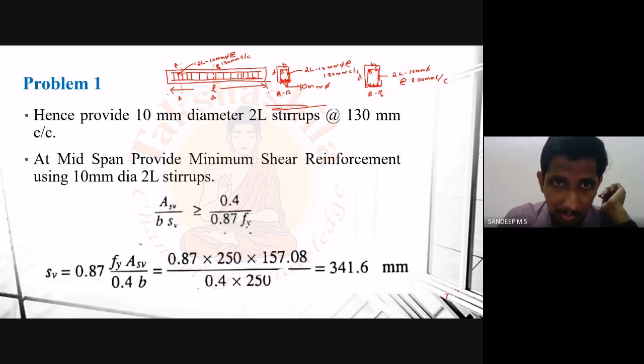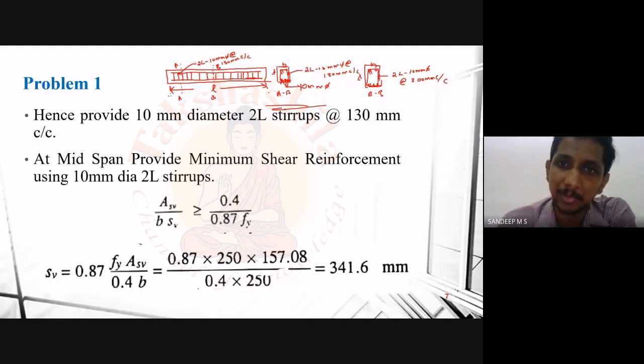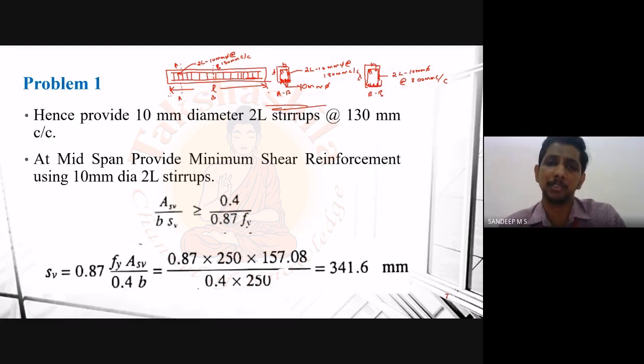Okay, and regarding these arrow marks and other things, you have some suggestions or some guidelines from your Indian standard, and I hope you have already got this SP34. So that is actually showing the details of how you can provide the drawings. What are the details that should be included in each type of drawings? In detail, they have provided for beams, columns, beam column junctions, walls, and all the things that we have in our structural design. Those details are actually given by the code itself.